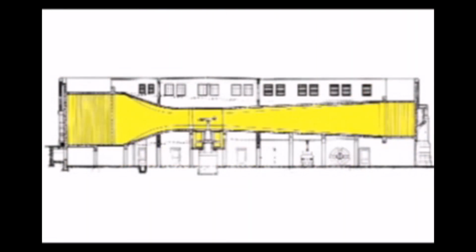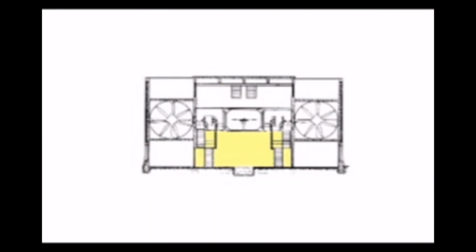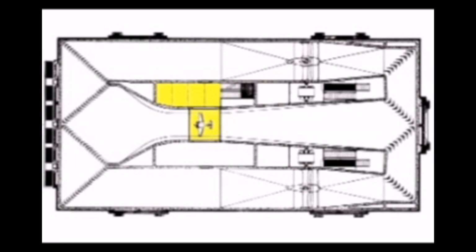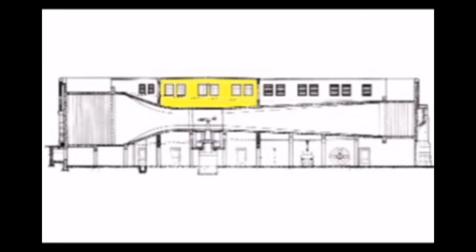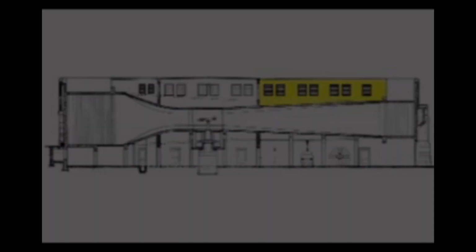The building is comprised of brick and concrete and has 3 main levels. On the ground floor is the loading bay where the drive system, auxiliary motor generator, calibration model, and vehicle ground plane are located. Also on this floor is the model shop where you'll see all the model preparation area, tools, and data storage vault. Going up to the second level are the fan decks, test section, model deck, balance deck, and observation deck. On the top floor are the traverse deck, control room, and customer room. Here's where the tunnel operator's console, the data acquisition and reduction station, and the customer offices are located.